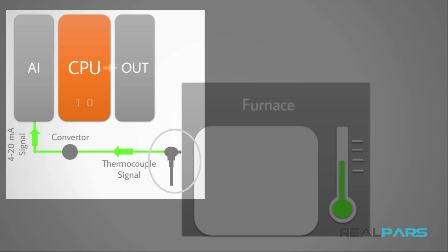So now, should the output module be a digital type or an analog one? In order to determine the type of the output module, we first need to see what type of actuator we need to connect from the output, and then based on the signal that this actuator receives, we can determine whether we need to use a digital or an analog module.